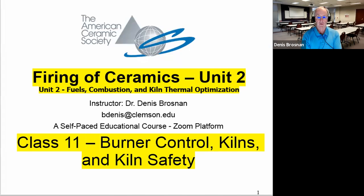But we talked in Unit 1 about vitrification, about reactive sintering, and about solid state sintering, at least to the point that we talked about changes that happen within the body itself that we are firing, the ware that we are firing. And we learned basically that whenever there's a linear change or volume change involved, we typically will slow down the firing schedule in order to not cause cracking in the body.